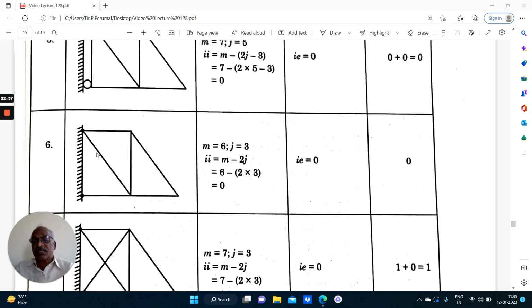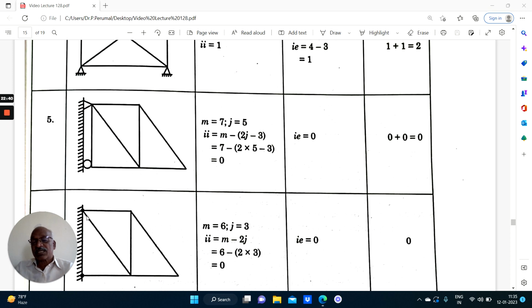Now coming to this truss, you have to understand the difference between the two cases. Here it starts from a rigid base. Therefore, this need not be considered as a member. Joints 1, 2, 3 only. We need not bother about these 2 joints. Let us avoid confusion, right? As far as the vertical support is concerned, either the joint or the member need not be considered. So you have 1, 2, 3, 4, 5, 6 members. Coming to joints, pin joints 1, 2 and 3 only.